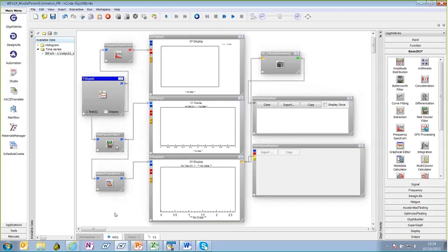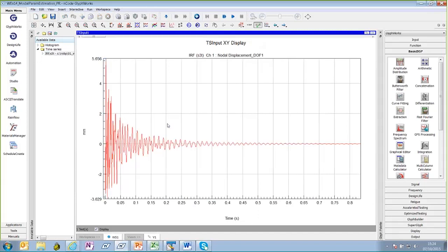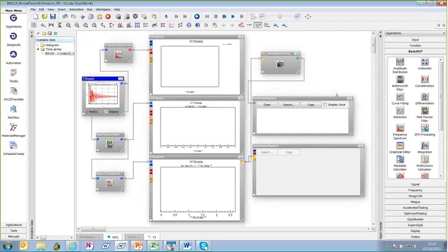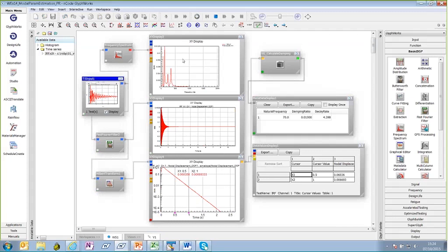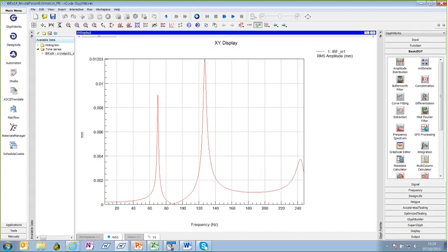In a similar way, as I mentioned, you can also use it for looking at the decay of a signal and looking at the damping. This is a measured set of data where we've got a single degree of freedom system with a damped system, so you're getting decay of that signal. Now, if you've got enough resolution, you can, in the frequency domain, look at this and find the damping by finding the 3 dB drop-off point, and that will give you some measure of the damping to the peak. But if I run this process, the accuracy you can get is defined by how accurate your PSD is. So you have some resolution issues with the PSD, based on what the sample rate and the frequency resolution you want is.